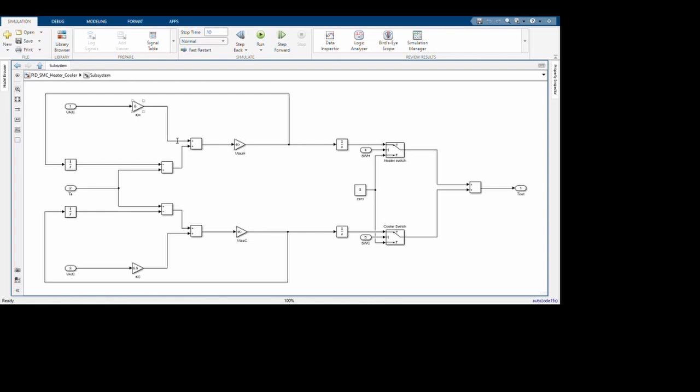Now you'll be noticing this is called KH, which is the heating gain, which I've kept as 5. And you'll be seeing KC, which is a cooling gain. Now I've reduced the cooling gain from 5 to 3.5. The reason is because most air conditioners in our homes today are 3 stars, and most 3-star ACs have a COP, or coefficient of performance, of around 3.8 to 3.9. The reason why I've kept 3.5 is because this is a very ideal equation, so we need to lower our expectations in that case. I've kept the time constants the same for both because it's not going to make much of a difference. It is 10 seconds for both of them, and the value is called tau.